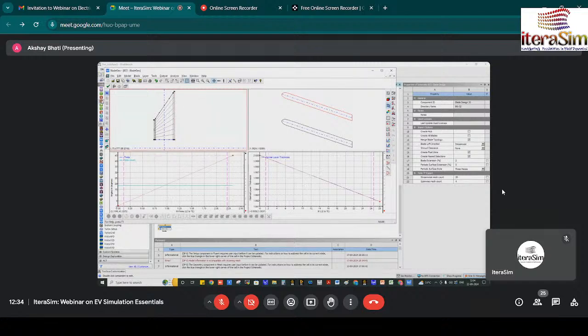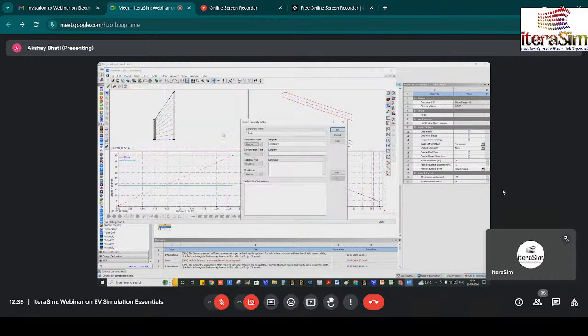Okay, and now first one, there are a few options here. First, we come to the model. In the model, you talk about what you are generating, a blade, and you need to specify the component type. It should be fan. You can develop it differently according to the requirement. It will change the configuration and everything.